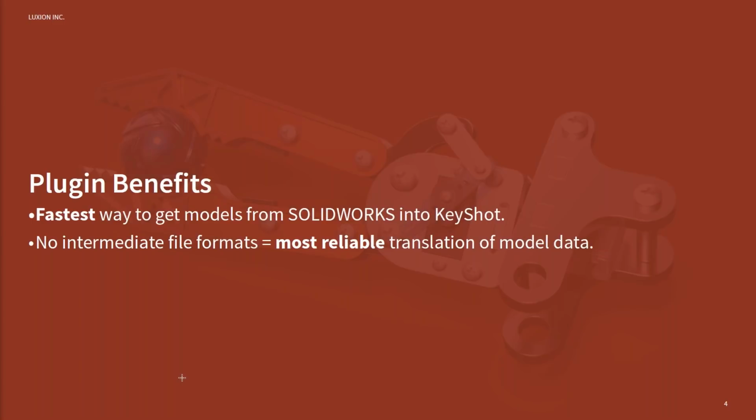Again, it's most reliable to go straight from SOLIDWORKS to KeyShot using the plugin. And if that's not available, which it should be for everyone, it's free to download, and you actually don't need KeyShot installed in order to download it. So I would recommend using the plugin as the first option, the native CAD format as the second option, and avoid those step, IGES, kind of third-party formats if possible.